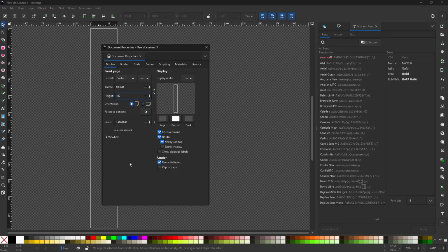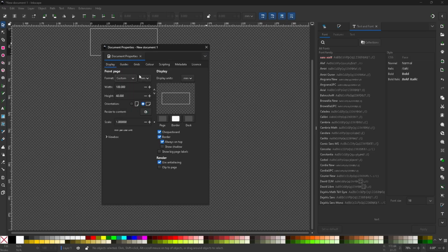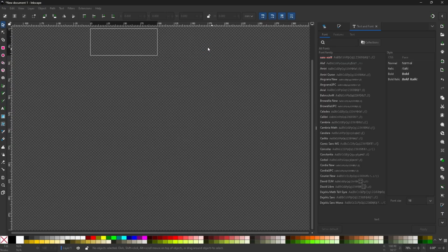So go ahead and make sure everything is the right size. In my case, I'm making the document 10 millimeters smaller than my actual piece of work. So the material is going to be 10 millimeters bigger, and that'll help me get it clamped on and everything. Don't forget the units. In my case, I work with millimeters.